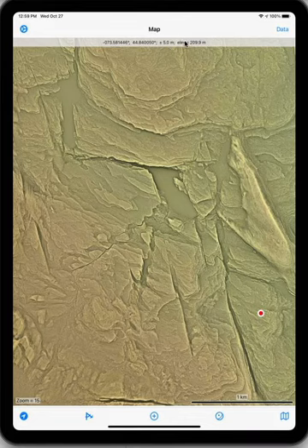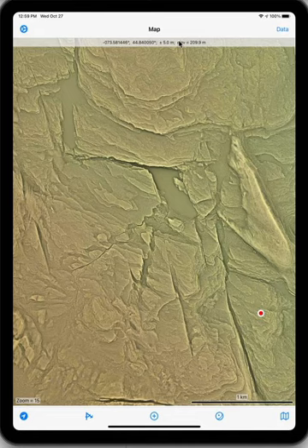And it also gives you the elevation. Because we've loaded a digital elevation model, we know the elevation of every point on this map. Now, importantly, this also gives you the uncertainty in your location, which can range widely. And if you're going to make observations, you want to wait until this uncertainty level drops below 20 meters or so to get the best precision.